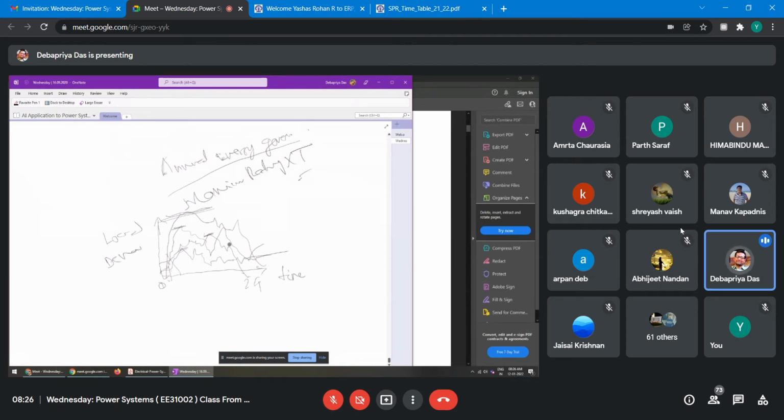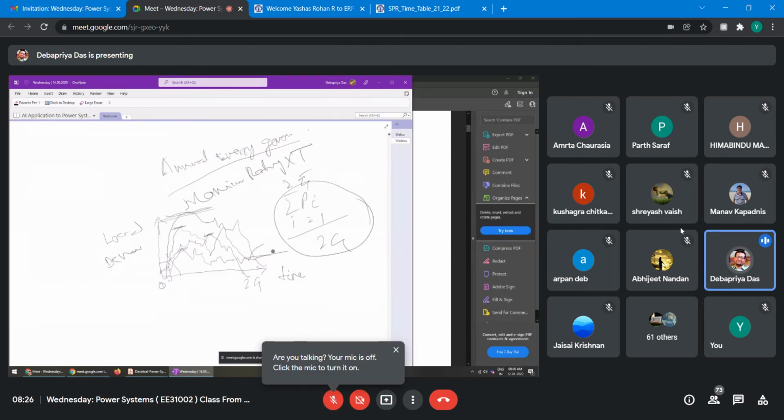This way, every hour you add all the loads of the 24 hours: the sum of Pi, with i equal to 1 to 24, divided by 24. This will be your average load. And as you do this every hour, whatever the peak is, that is your peak load, for the combined one. The average load divided by this peak gives you the average load factor.